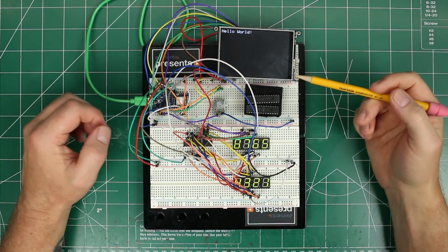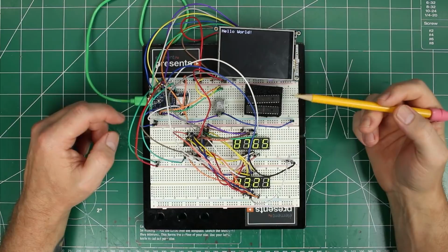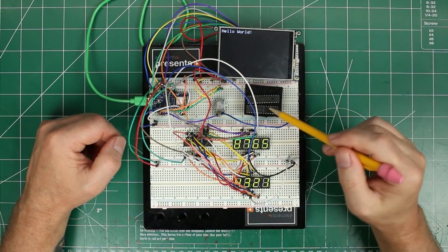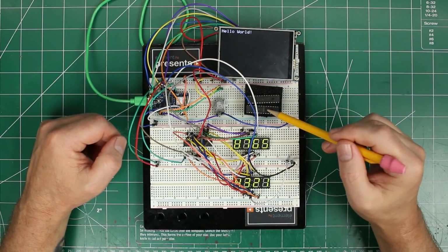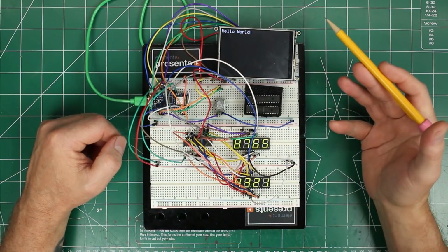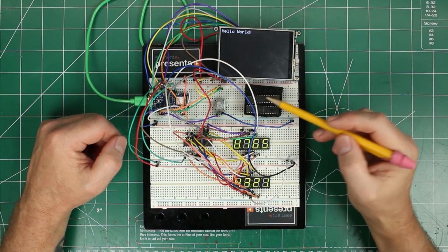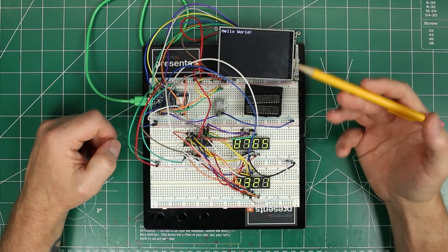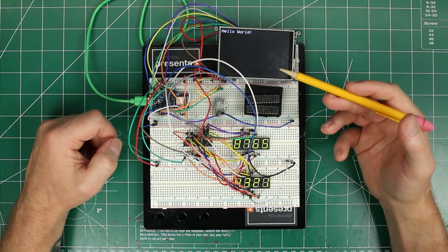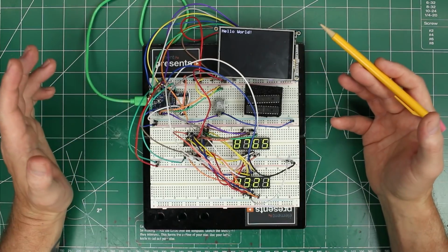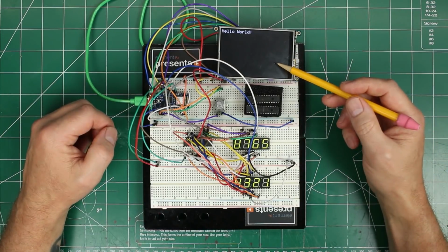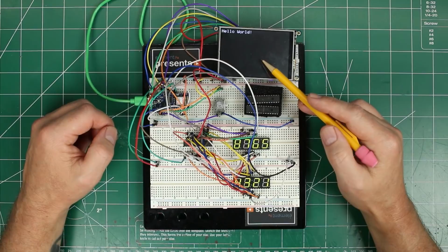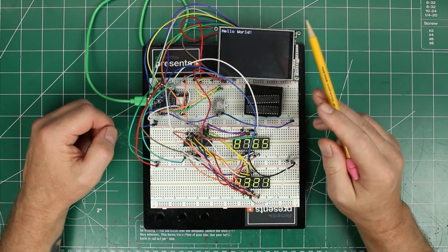I ended up talking to some of the folks on the Adafruit Discord channel, because I was using the Adafruit library for this, and they pointed me to a function that would write all 16 pins all at once. So that sped it up significantly, and that totally worked, and I was happy with it. Then I moved on to work on this portion a little bit, and what I found was when this writes, it's blocking.